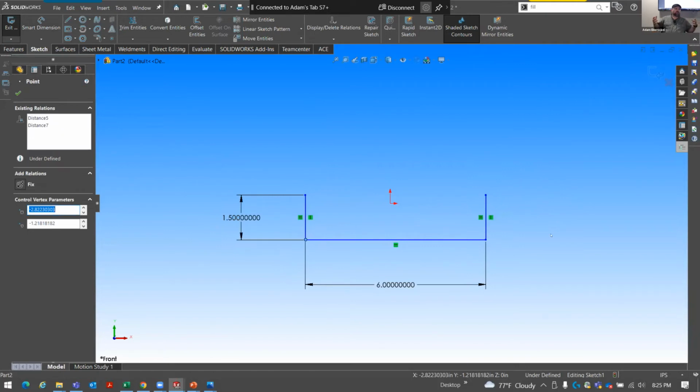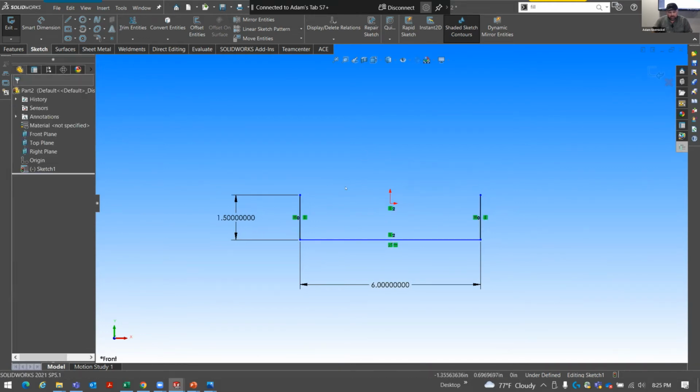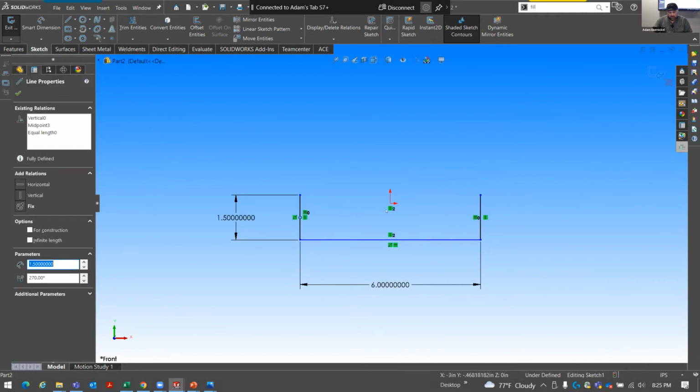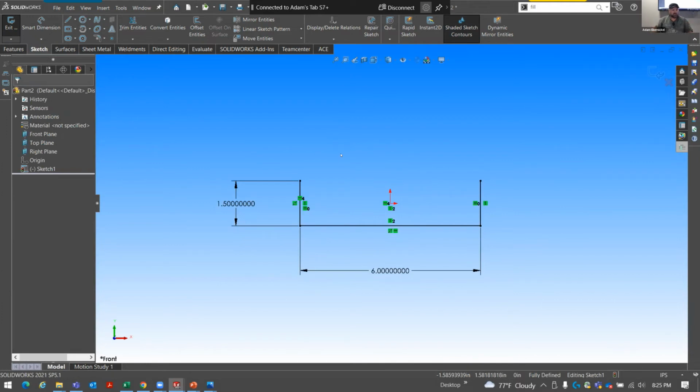If all else fails and you don't have a good design intent and you don't have a reason for locking something to the origin on a corner or extruding out in one direction, my opinion is, and this is my opinion, that if you don't have any other reason to do that, always center your sketches about the planes. So I'm going to grab the midpoint here to the origin. I'm going to set that vertically, and I'm going to do the same to this one, except I'm going to set it horizontally. And now that's middle. It's kind of aligned with the planes and that orientation, right? Go ahead and use my breadcrumbs, the D key, bring that down here to me, check it off.